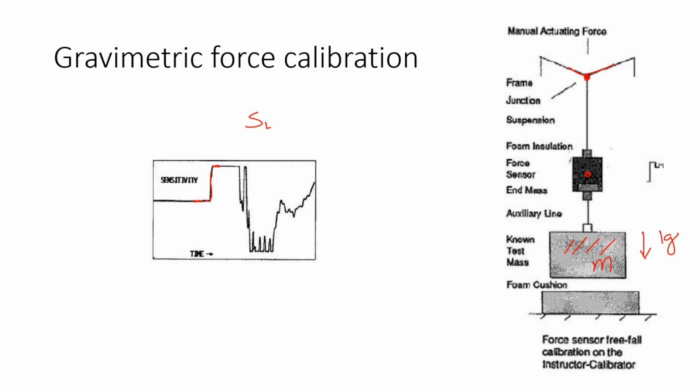We're going to say the load cell sensitivity is equal to this increase, which is in millivolts, divided by mass times acceleration. So the acceleration is of course 1g, and the mass is given to us, whatever numeric value it has. And we're going to demonstrate this experimentally as well.